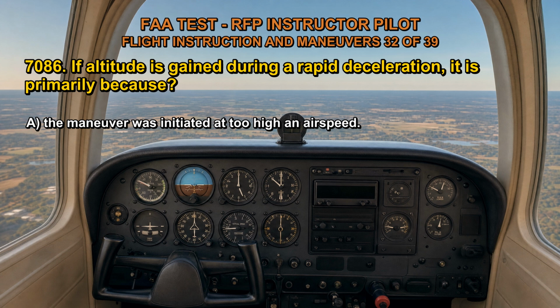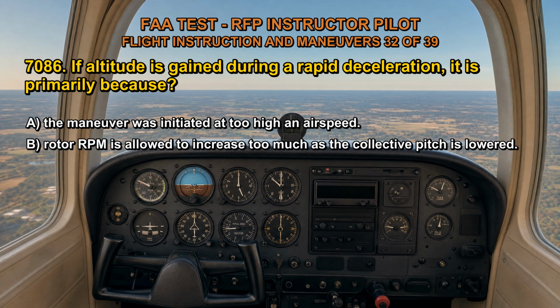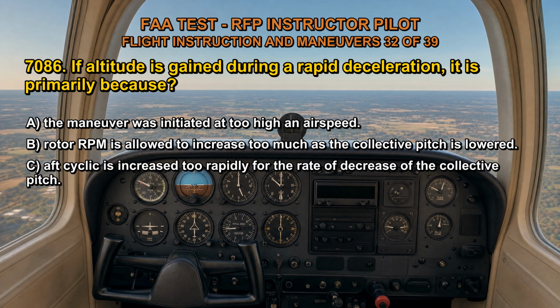7086. If altitude is gained during a rapid deceleration, it is primarily because A. The maneuver was initiated at too high an airspeed. B. Rotor RPM is allowed to increase too much as the collective pitch is lowered. C. Aft cyclic is increased too rapidly for the rate of decrease of the collective pitch.